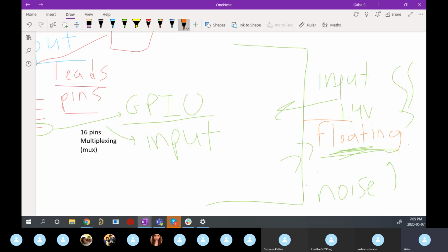So the pull-up and the pull-down resistor are a fantastic tool because they allow you to define your states properly. Let's say I enable a pull-up, right? What that means is that internal to the microcontroller, this is not external, this is inside the chip, I can enable a resistor, which is really cool. I can turn on a resistor, which is kind of weird when you think about it, but that's what's actually happening. There's a little switch that connects this resistor path to my pin.